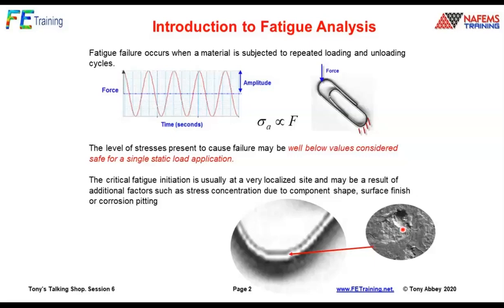Fatigue analysis is rather curious. Strictly speaking, it's about the life to initiation, not the life to actual crack and final failure. That's sometimes a little bit difficult to accept. High cycle fatigue, which we're going to talk about, is certainly that kind of issue. The idea is the actual time spent cracking and propagating is tiny compared to the initiation part. So our fatigue life is really fatigue life to initiation. There's a big gray area, that's another big subject, but that's basically the idea we're going to start to talk about.